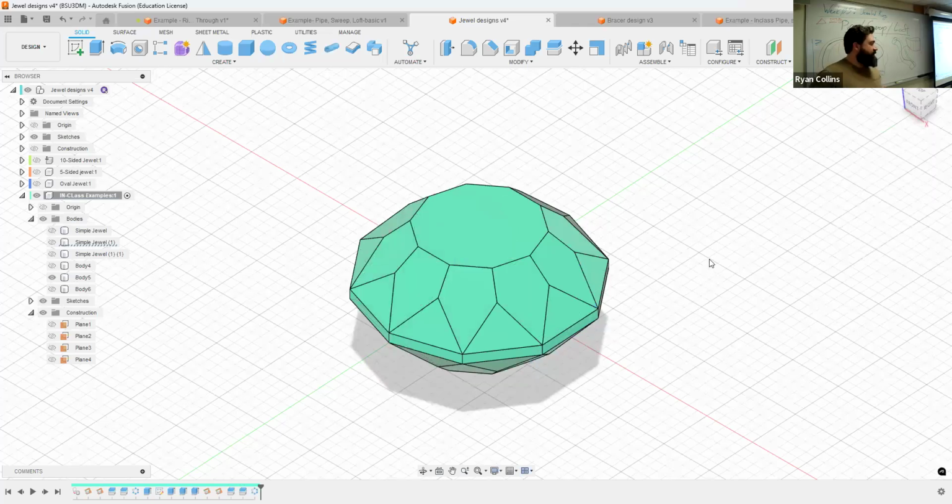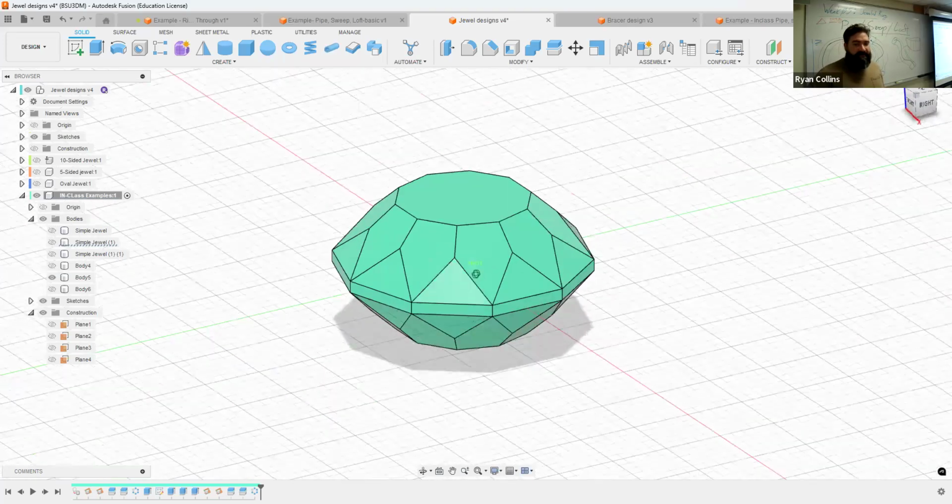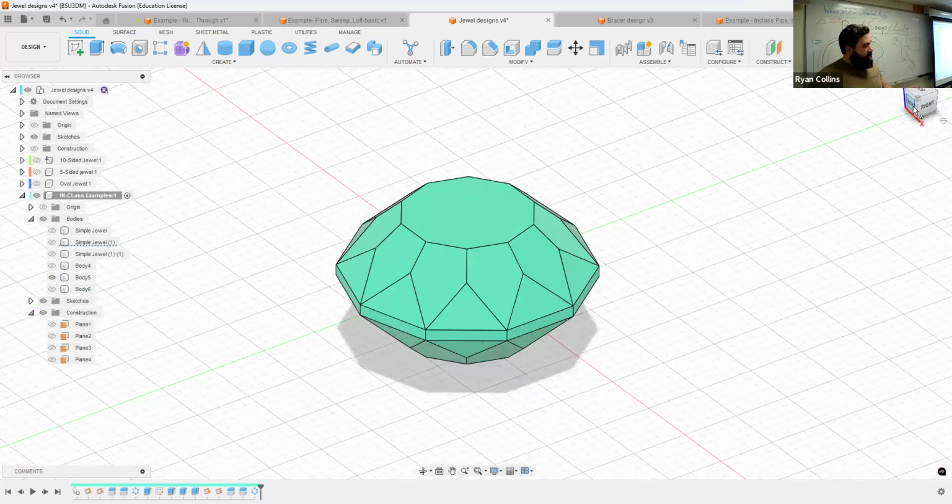And that looks crazy complex right now, but this will allow me to make fancier jewels, just because they overlap and such. So I'm just doing the exact same thing, just doubling the amount of faces, so long as the doubling matches the number of faces you made for your polygon. So if you made a 10-sided polygon, you can bump this up to either 5 or 10, as long as it's evenly divisible. Make it 12, 6 faces, or 6 instances, or 12 instances. 14, 7 or 14. You get the idea. As long as you can divide that by a whole number, you're good.